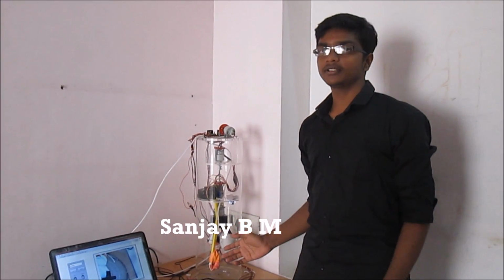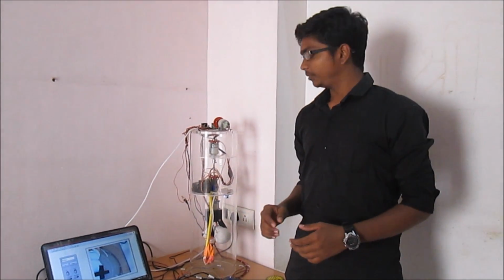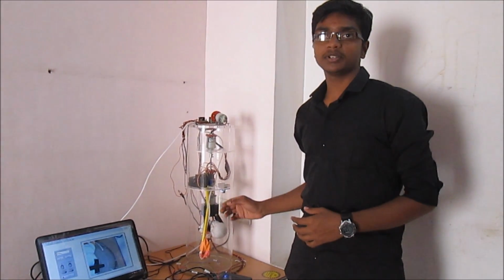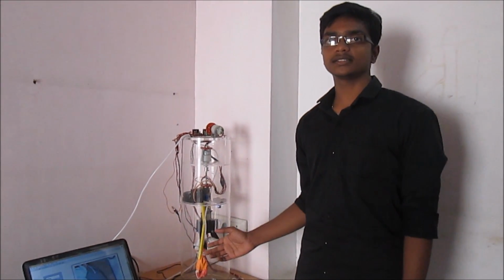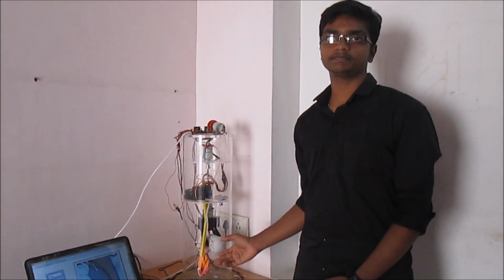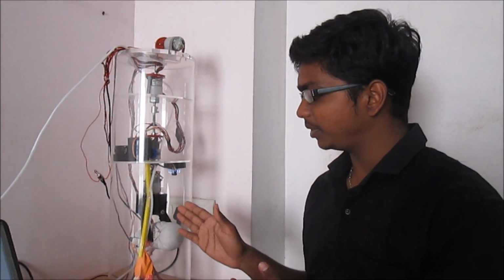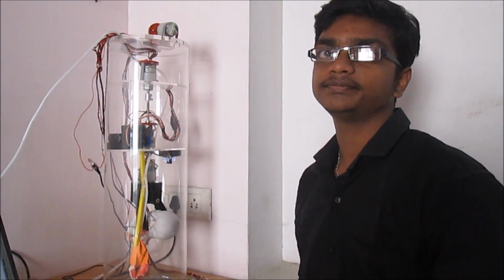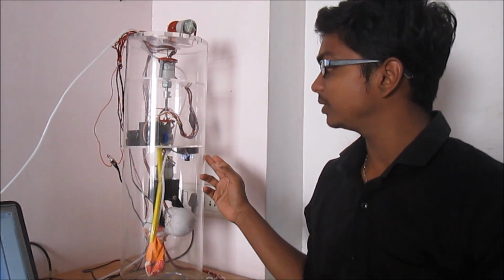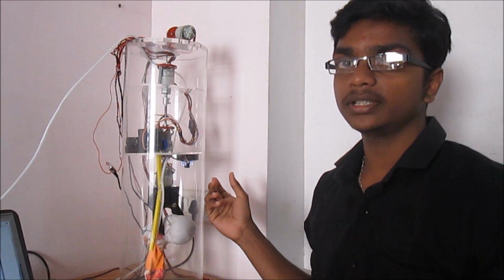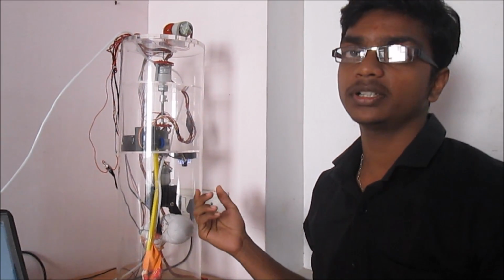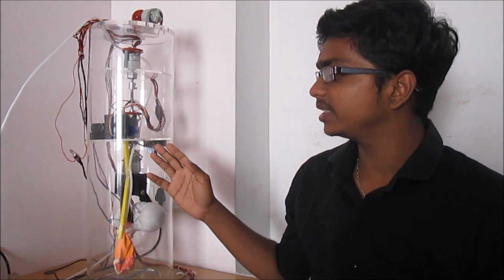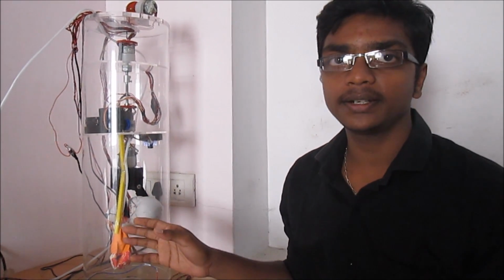By using this technique for the rescue operation, we can avoid the chances of the child slipping further down, as the child has support both from the bottom and the top. Since the idea is to provide bottom support, tracing the gap between the child and the wall of the borewell was the biggest challenge. So, we used a camera with a light source, attached it to the disc and provided rotation for the disc. Now, by rotating the base disc, the gap can be easily traced.